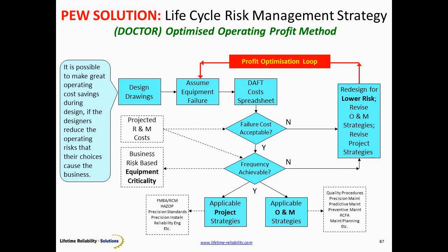If that bearing fails, this shaft gets damaged, I've got to buy this from Europe, it's going to cost this much to get across. We can put a cost of the consequence of failure together pretty quickly. Once we know the cost of failure, the question then becomes how often can we afford that cost? So we go in and say, well, is the cost of a failure acceptable?